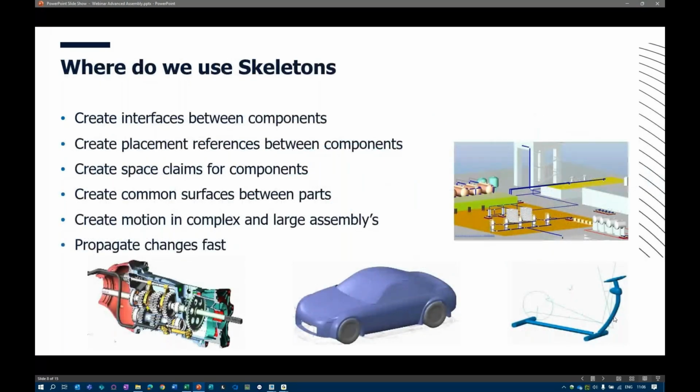Where do we use skeletons? There are different methodologies, different reasons why we could use skeletons. First of all is to create interfaces between components, like you see the transmission here on the bottom. On all those housing parts, we need openings for the central axis, and so these are needed in multiple parts.